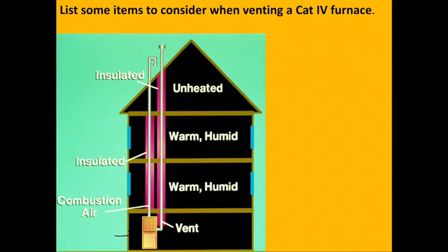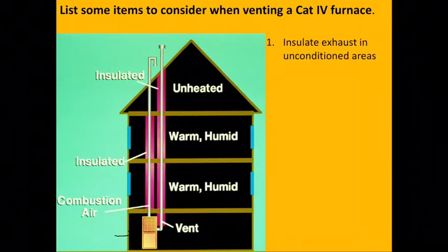Now, they may be using a concentric vent or something maybe a little cleaner to the eye, and it works fine in some applications. It doesn't work fine in all applications. So let's take a look at some of these. The first rule that I would say is a good recommendation is to insulate the exhaust in these unconditioned areas.